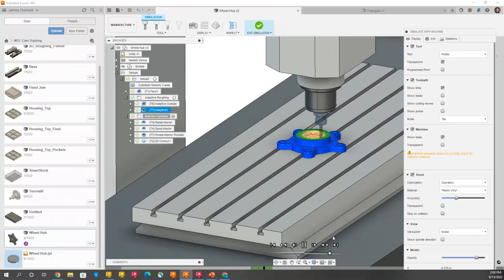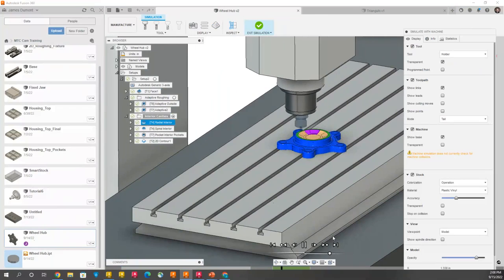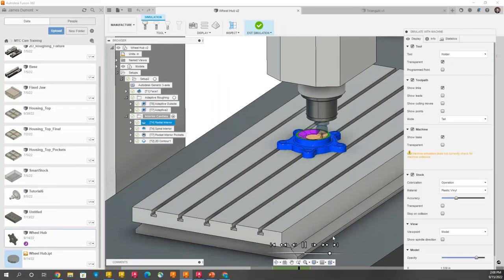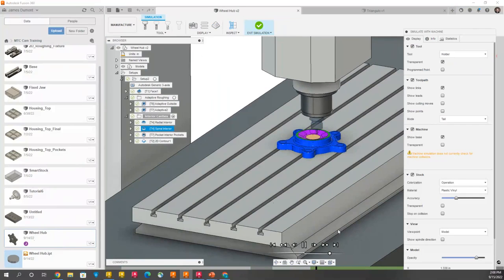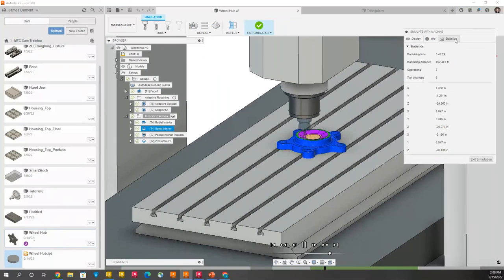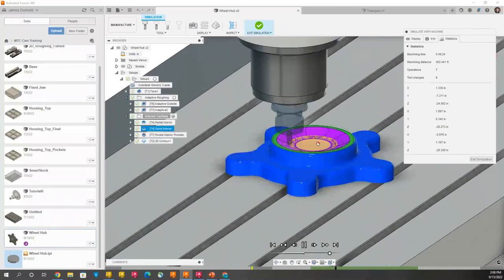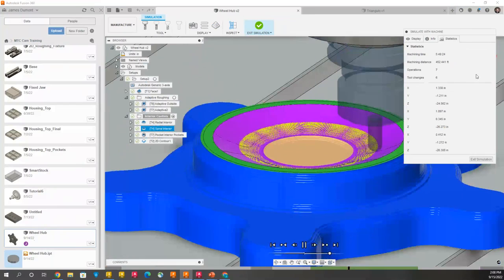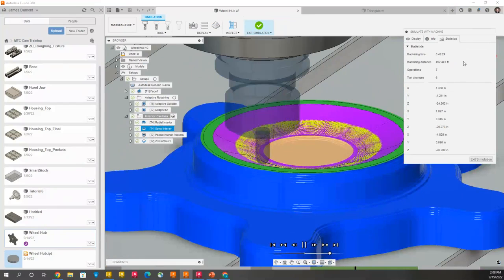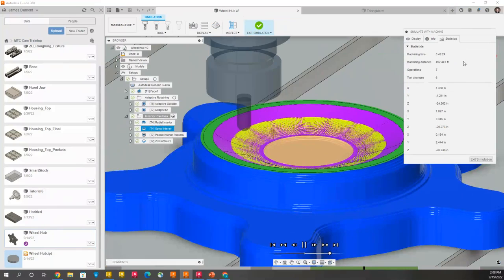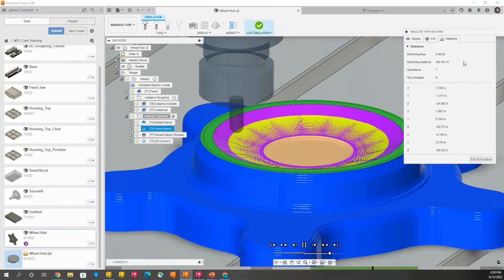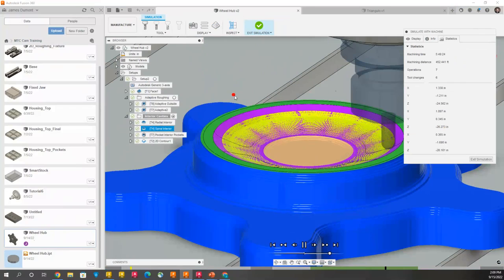And if you've never seen this before, right now, the machining that I have takes all of the feeds and the speeds, everything that I've defined in my tooling, and gives me an idea about how long this will take to machine. And right now, because that conical surface is rather intricate, to get a nice finish, I'm just under 6 hours for machining. I can get times for each toolpath or for the entire setup.